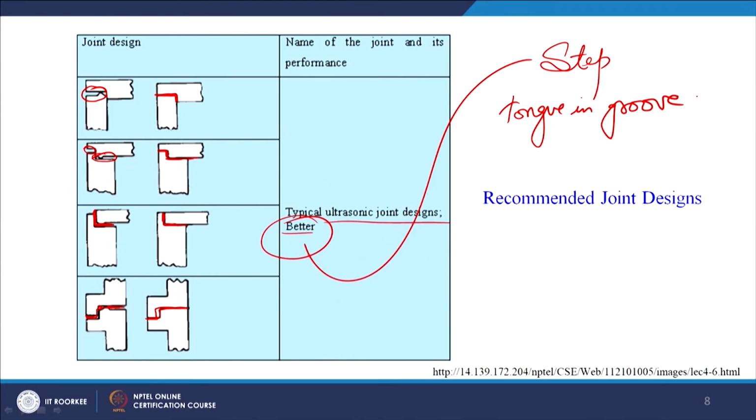Now depending upon our product design, whatever possibilities exist, if we have the idea about different types of joint configurations, we can select the best joint configuration which can give us a high strength, minimum warpage, minimum flash. So accordingly we can join the two parts together according to our design. So during design only we must keep in mind all these joint configurations which are possible for ultrasonic joining of plastics.